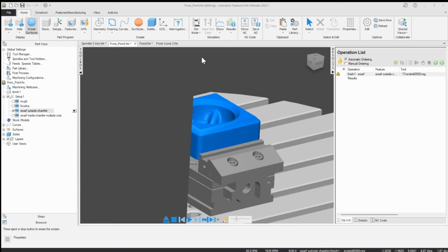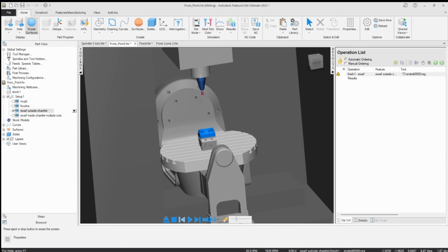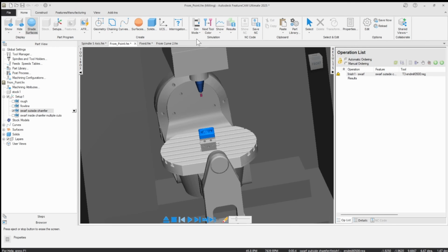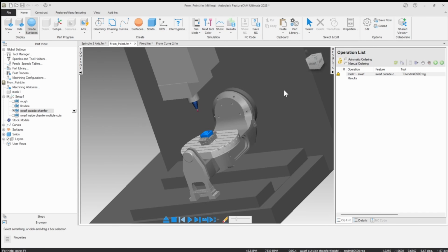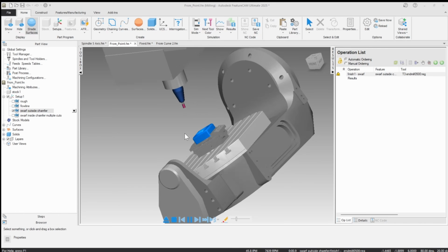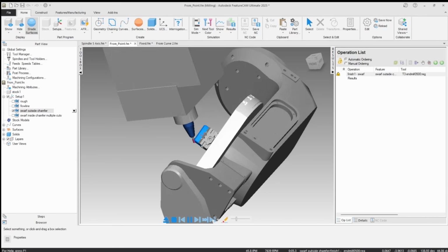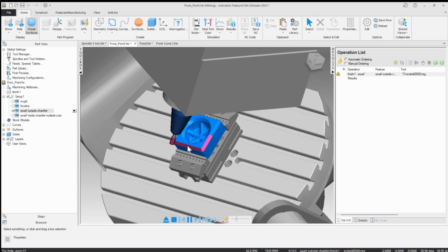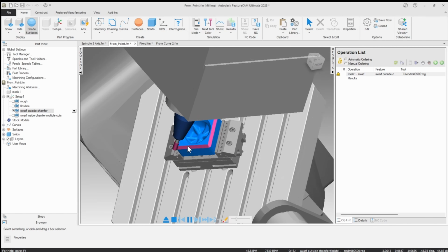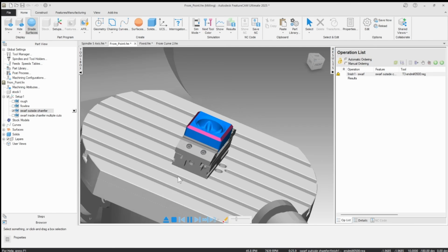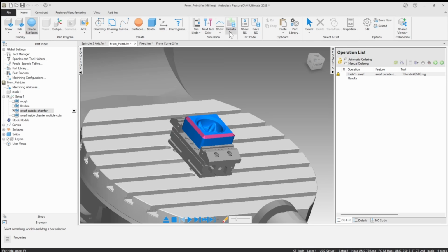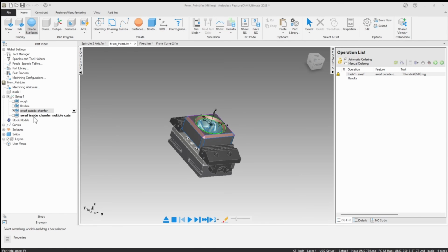This will calculate the toolpath using the machine as well. All right, so we've got this nice look. Again, I'll hide those pieces, whatever you want to do, just to make it easier. Again, you can have that stuff stripped out if you don't like it. And we see we're doing a nice swarf. So instead of doing a chamfer toolpath, we can just tilt it over and do that chamfer with the swarf. All right, so the next one I want to do is showing you a swarf that has multiple steps to it.